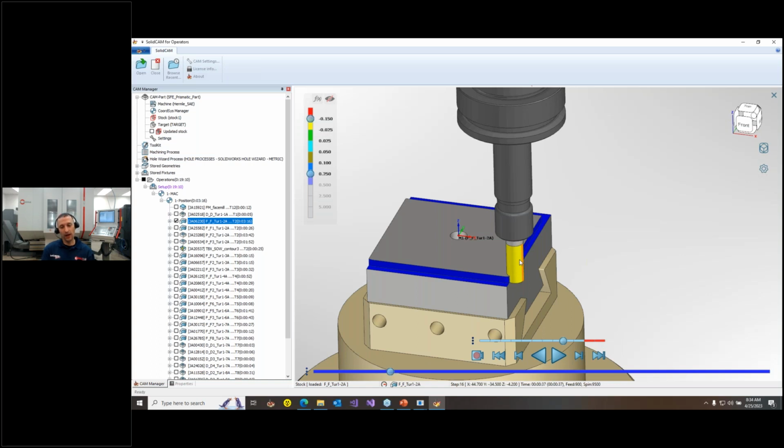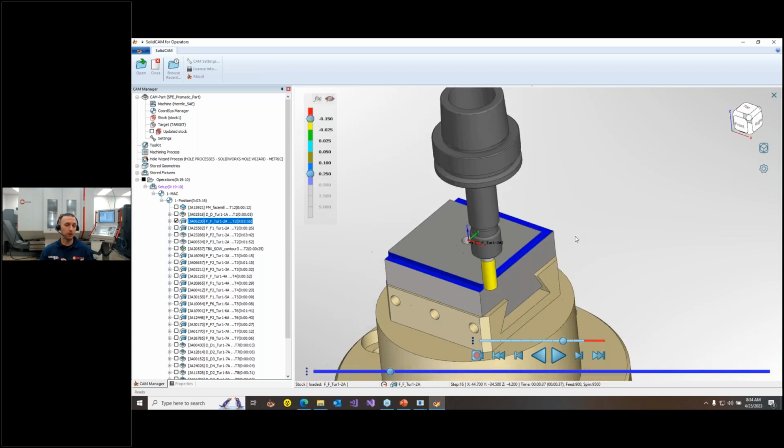So what I like about SolidCAM for operators is that you start to see the same software as the programmer and the operator, and you can connect and talk to your operators and explain this stuff. Here, as an operator, I made a simple change. I just wanted to add extra passes around it. Well, you see now, technically, I didn't need extra passes on the right and left because there's not as much material.